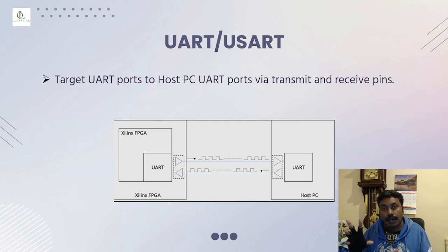So most PCs will have that, whereas some microcontrollers may not have support for USART. It may have a UART. For example, the 8051 has only UARTs, it doesn't have USART. So likewise, you have to check with your microcontroller and be familiar with what communication mode that microcontroller uses.